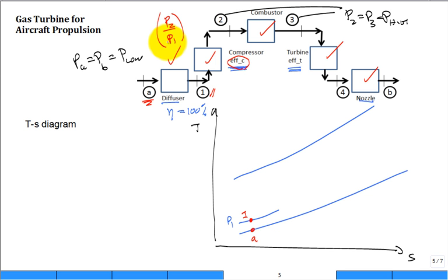All right, now, let's say it's 8 or 9 or 10 to 1, and then boom, you're going to go up, but you're going to do this in 2 steps. You're going to go straight up to state 2s, and then because of the isentropic efficiency, you're going to calculate 2 actual, the temperature at 2 actual, which has the same pressure. And wouldn't that state be over here a little bit? Wouldn't the actual 2 be right there? Yeah, we've done that before, haven't we?